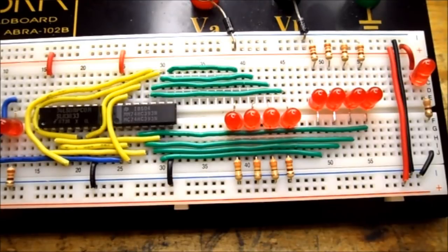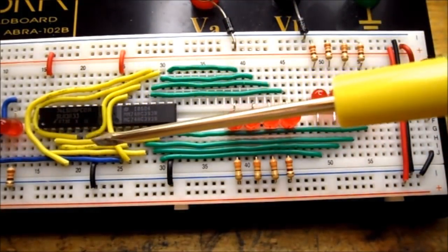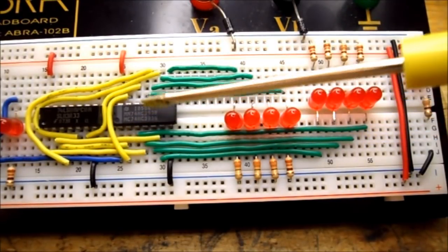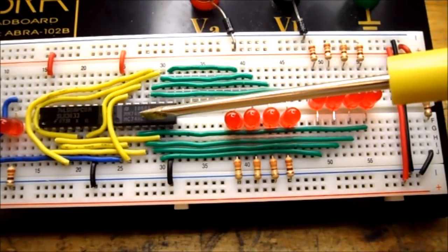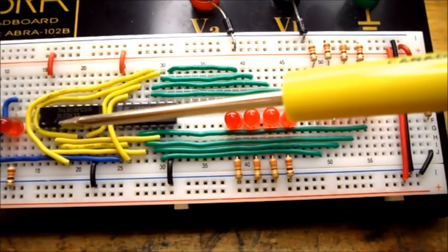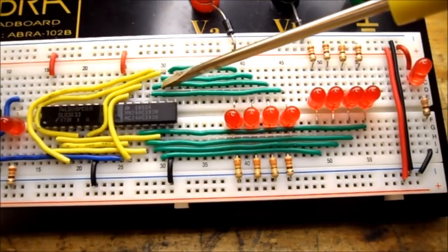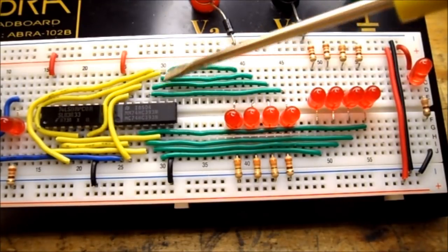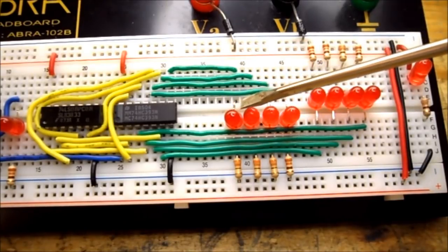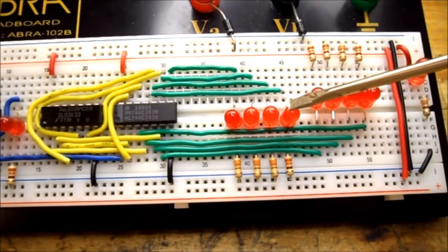So this is my circuit wired up, and you can see the original clock signal comes in on this blue wire and goes to my counter. So this is the 393. That means that this one has to be the 7408, and I'm going to use two AND gates on it. You'll notice the outputs for the most significant digits go straight over to the LEDs. So this is my most significant digits, and that's going to count 0 through 5.